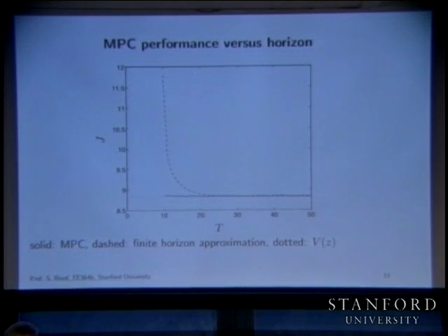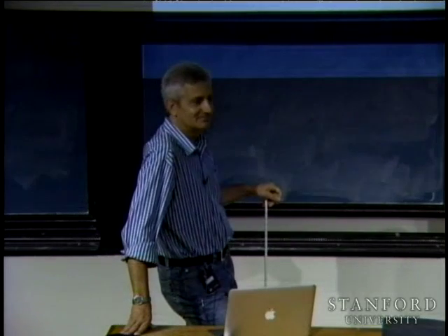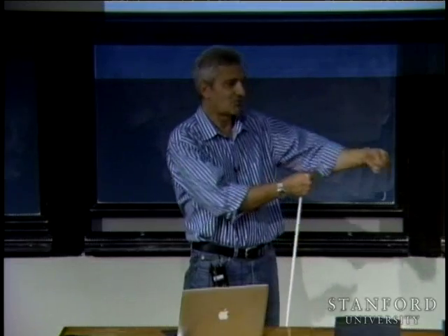If you look at your first MPC iteration, it will see that as if you are incurring a cost of 11.5. And then it will realize that I have only used the first input, so my cost is going to reduce. What happened, let's say for this MPC thing, on the first step, is it's actually quite rushed. Because it's basically saying, you minimize this cost, take the state to 0 in 11 steps. In 9 steps, it's impossible. It's not even feasible to do. So it's feeling quite rushed, and it's got some input that just barely does it. Then the next step, the horizon moves another step forward. So I think they're perfectly okay. They're showing different things, but it's okay.